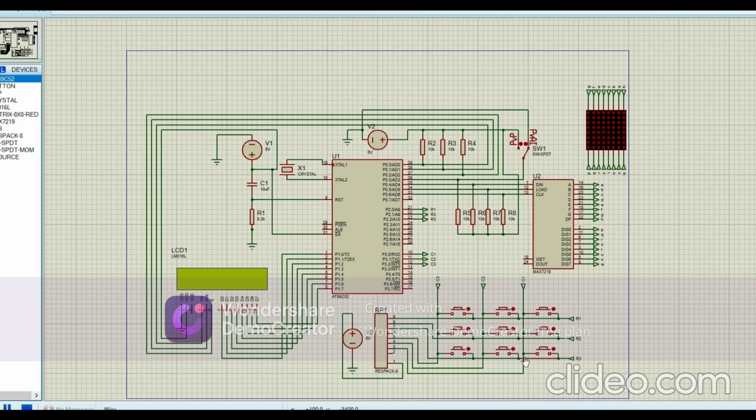For output unit, we use two devices together. First, the 16 by 2 character LCD. This is our primary status display. It shows title screen, current mode, player versus player or player versus AI, then the turn, cross or zero, a compact text board, and win or draw message.